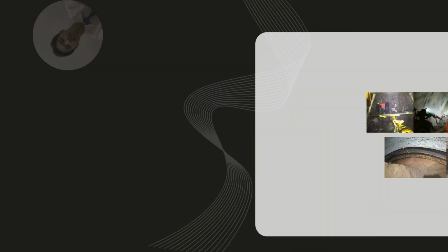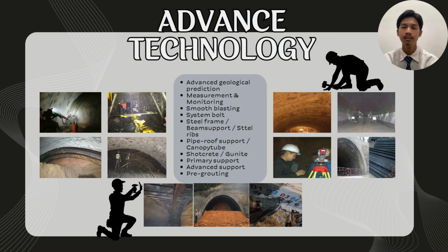So I show some of the advanced methods and tools used by the contractor to make tunnel work safer and more efficient. First, geological prediction. Before digging, the team used surveys to check the ground condition ahead. This helped them to prepare for weak rocks or water problems. Second is the monitoring system. While digging, they use sensors and regular checks to watch for any movement. This helped them fix problems early before they become dangerous.